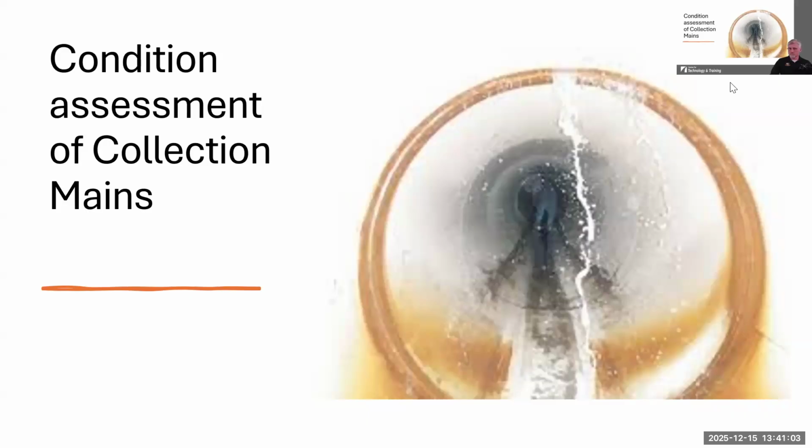We had a comment from Daniel that water-powered sump pumps are even worse on inflows, and just wanted you to know that was shared. That is true, because they use a lot more water. It's a jet pump. It pushes water through to pull the water out of the sump. So that contributes orders of magnitude additional water. So yes, definitely.